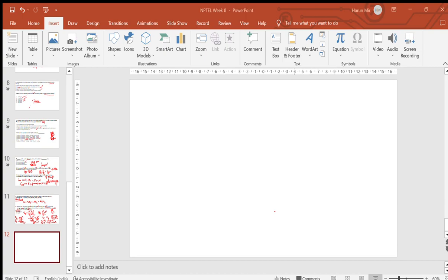Is it like 1 to 40, anything? 40 was the threshold, 40 was the maximum, like optimal. At 40% you can achieve a successful molding. Less than that, you will not be able to have an efficient binding capacity. 40% is the optimal volume percentage of your binder addition. So any combination, every time it should be 40?